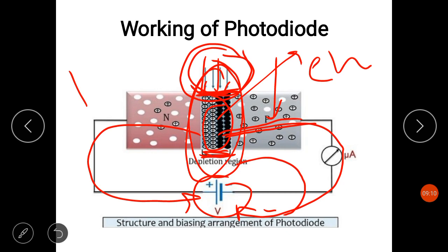So although this photoconductive mode is faster, that is the response time is less, it can exhibit more electronic noise due to dark current or avalanche effects. The leakage current of a good pin diode is so low that the Johnson-Nyquist noise of the load resistance in a typical circuit often dominates.